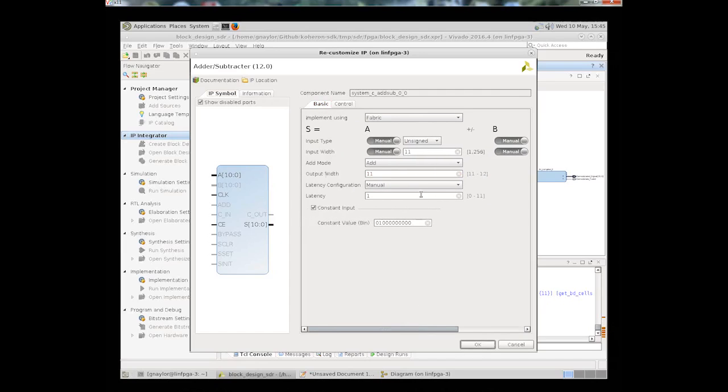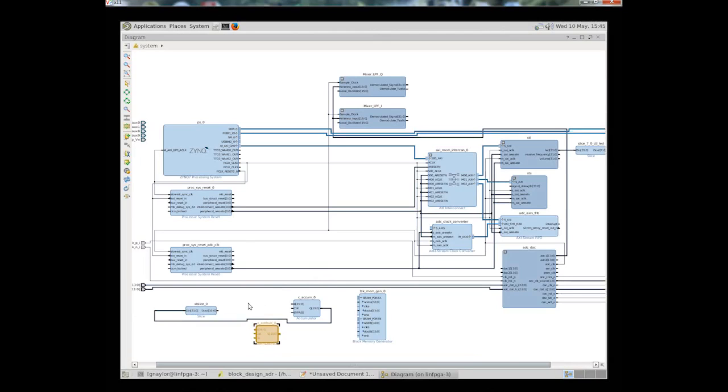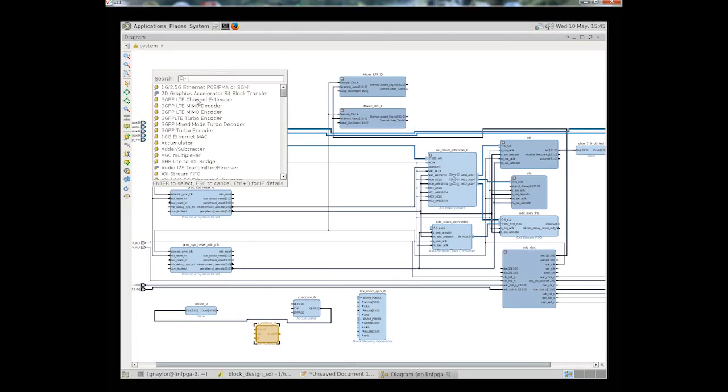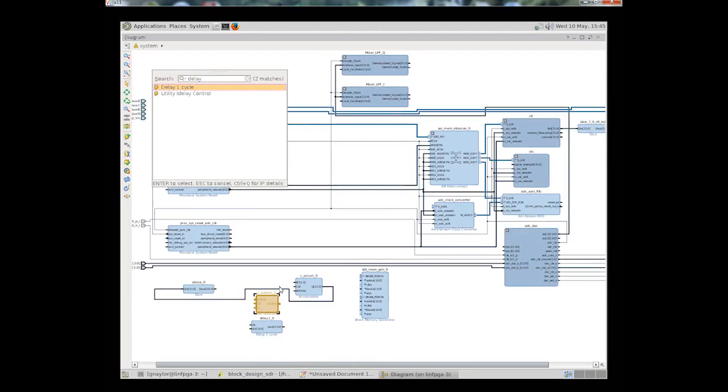Okay. Yep, everything's happy now. Okay, and so that these values arrive at the same time, because this will have a latency of 1, we'll just put in a delay block. This is actually one of our custom made blocks which has been brought in by the config.yml file. That gives us just a simple 1 clock delay. Now our clock, of course, we'll bring in later.